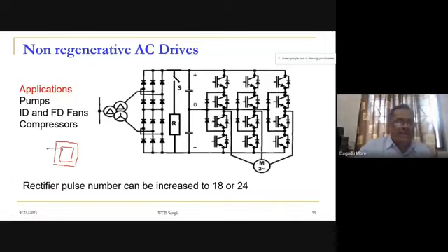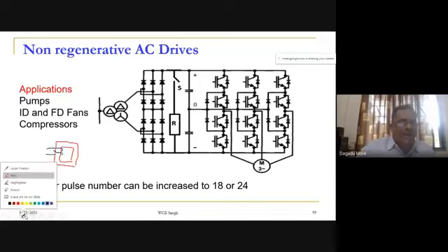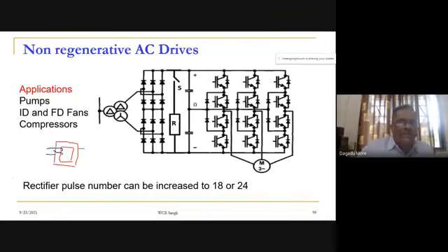I am having a single phase transformer with 7 windings on it. Can it be possible? What is your opinion? I have shown 1, and on the other side I am having 7 different windings. Is it possible? Yes or no? Yes, sir. So we can make a transformer with any number of windings on it, but we can give the supply to one winding, and the other windings can work as secondary. Any one of them may be a primary to which we can give the supply; the others work as secondary.